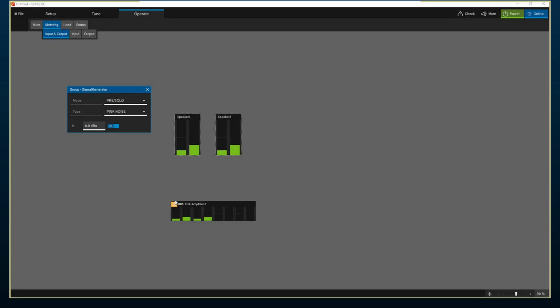However, this orange light did light up on the amplifier here, kind of that little check engine warning light. So I'm going to go to Load. Oh, and it's telling me right here, open load. So at this point, I would say we probably don't have a speaker connected, which is correct. Don't want to be blasting the neighbors out right now. But very, very quick and easy to give us a status of what's going on with the system. So we can go and start checking our speaker cables, plug them up, and be good to go.